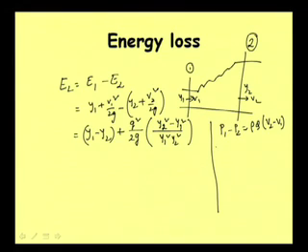Considering this as rectangular, we can write half rho g y1 square minus half rho g y2 square, equal to rho Q. As we are talking about unit width, and B is neglected because the channel is prismatic, we can write Q directly.